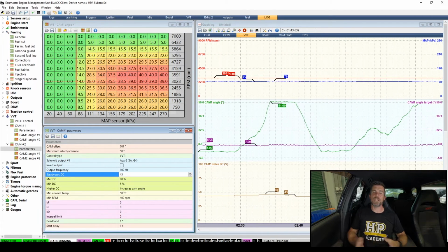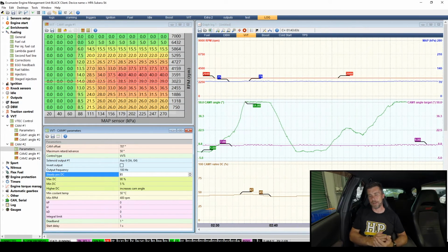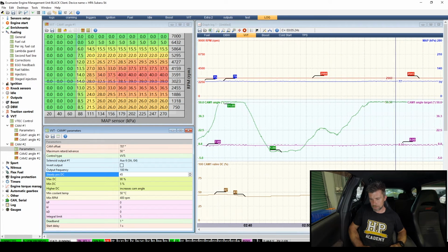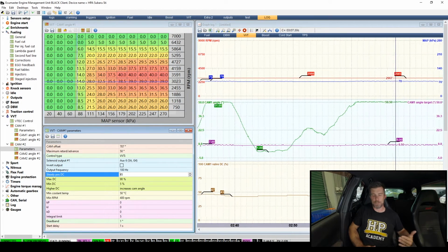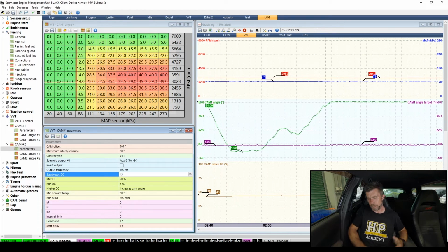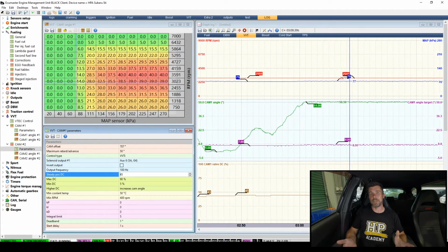It is worth mentioning that while we go through that process, we've got quite large swings in our cam timing. While I've been talking there, we can see we've gone through to maximum, which is about 50, 51 degrees. It's a good time to come down and fill out the maximum value here. This obviously is now different to our other bank of cylinders.